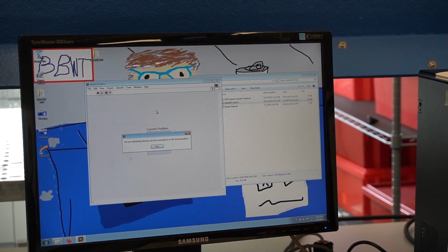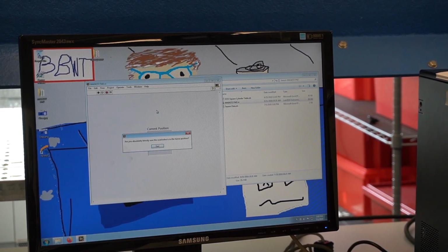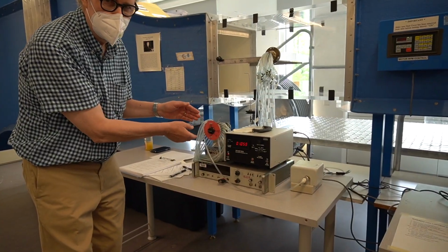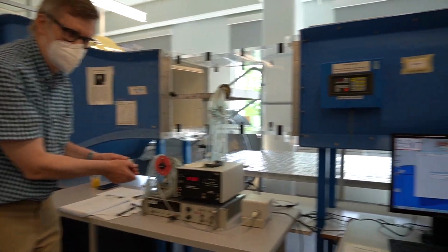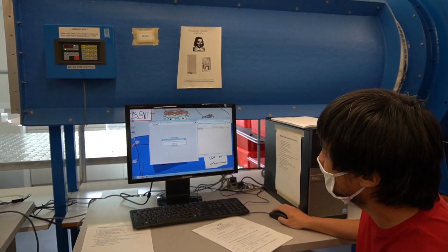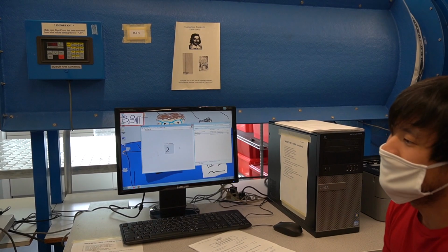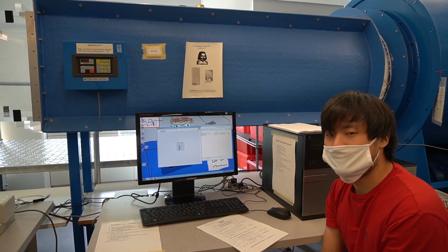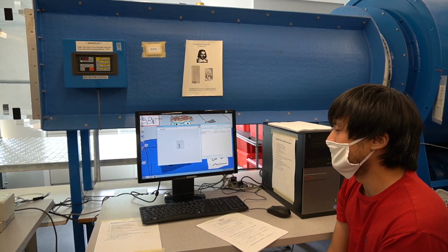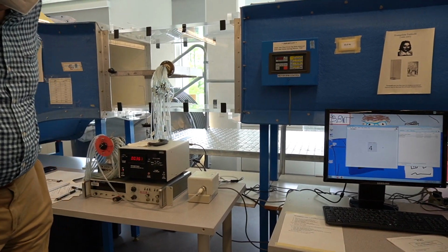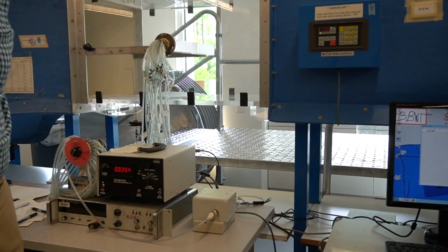It asks a follow-up, are you absolutely bloody sure the scanning valve is in the home position? And the answer is, again, yes. So now we can click yes again, this time with an exclamation point. Nice. Now you can see it's sampling each location using the LabVIEW VI, and it will record that data to an Excel spreadsheet, taking out the manual process of it.